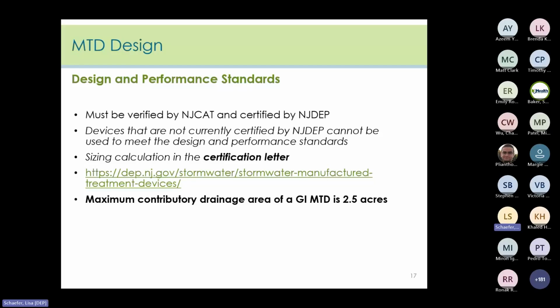Verified and certified. All right, you can't use out of date MTDs, and you have to follow the sizing calculation in the letter. We have the listing here, and we have the maximum contributory drainage area. And as I just said, the definition does not include the area of the stormwater management measure itself.